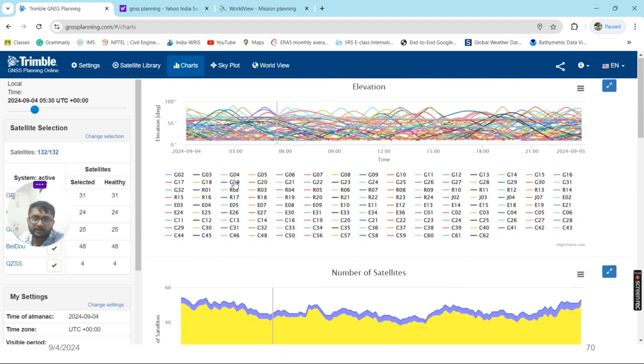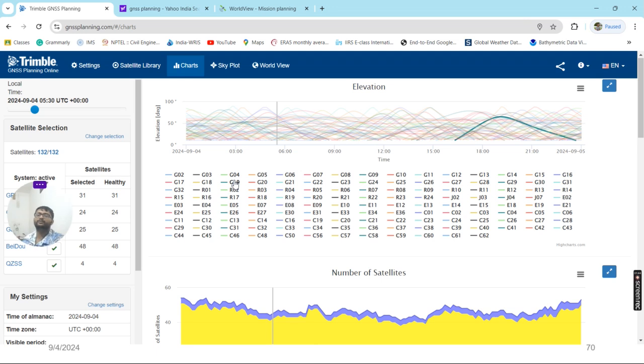So you can find out the timing during which you can do this GPS survey, because essentially for a GPS survey we need at least 4 satellites which will give us the particular location. Apart from these 4 satellites, our next criterion is that they should be available during the entire survey. Apart from that, the DOP value should be minimum and the ionospheric delay should be minimum. We should also survey when the tropospheric delay is minimum. We have to take those kinds of measurements while doing the survey, so that it gives us more accuracy.